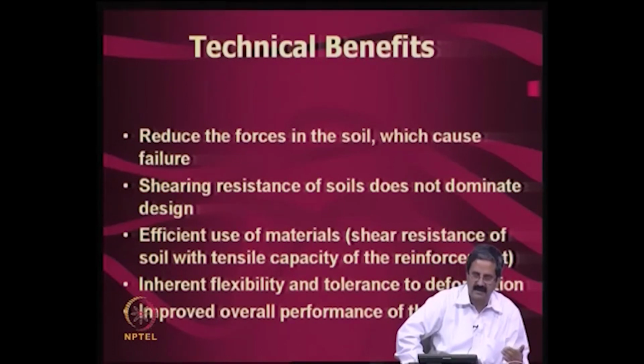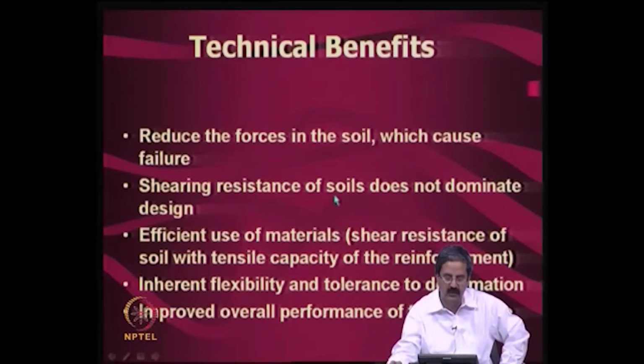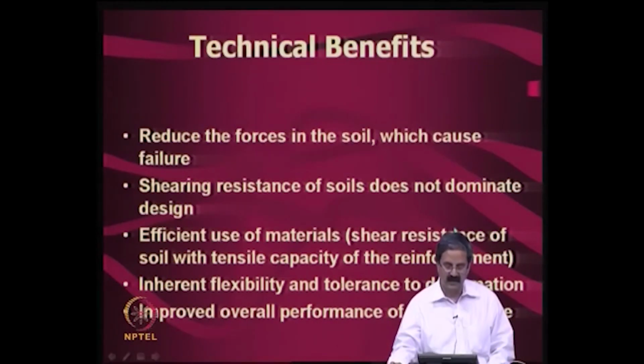Now with reinforced soil, you are able to give cohesion, and now the shear resistance of the soils alone does not dominate the design. We do not need to bother about whatever shear resistance is available. Now you are putting in a reinforcement and increasing the shear resistance, that is an advantage to whatever you want. So that way the shear resistance of the soils does not dominate the design.